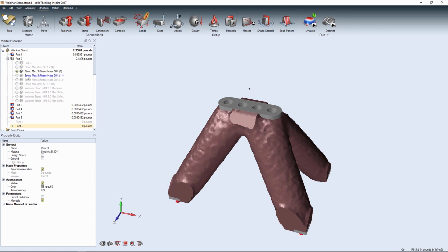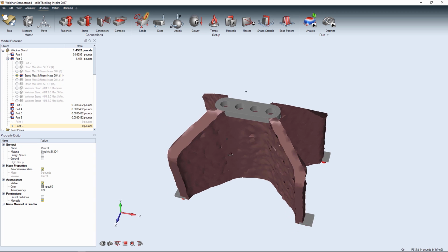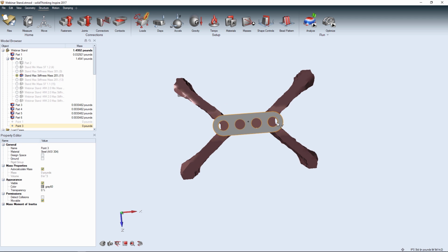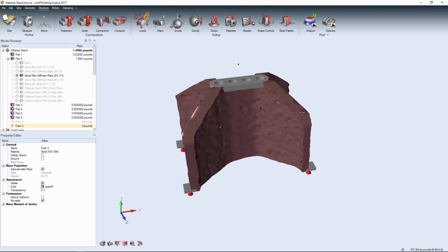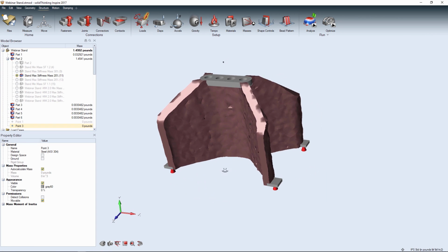Now, if I bump that down to 20% and added a shape control, this is the result. So this is the result of a 20% mass reduction, and the shape control was an extrusion, okay, which means that it had to be solid and complete in one direction, and that's this top direction here. So this could be like an aluminum extrusion type shape, or it could be a machined shape. But we can see how this is whittled down in the corners and in the center.